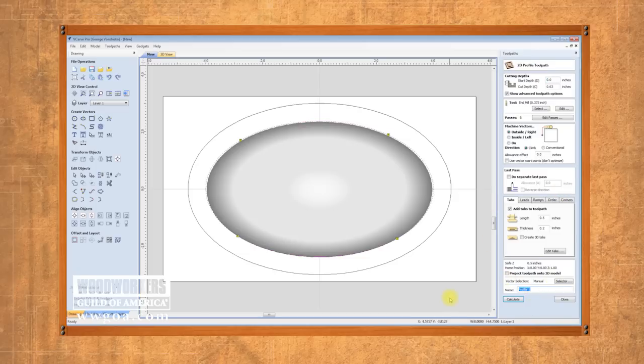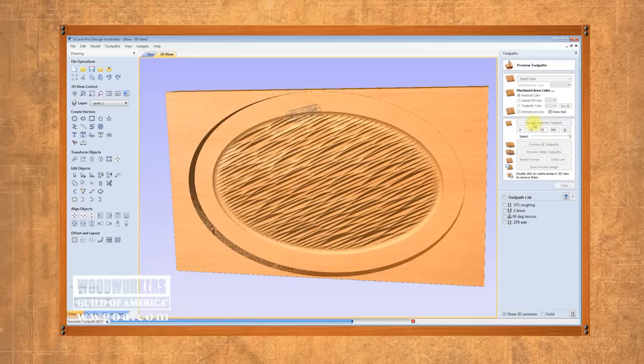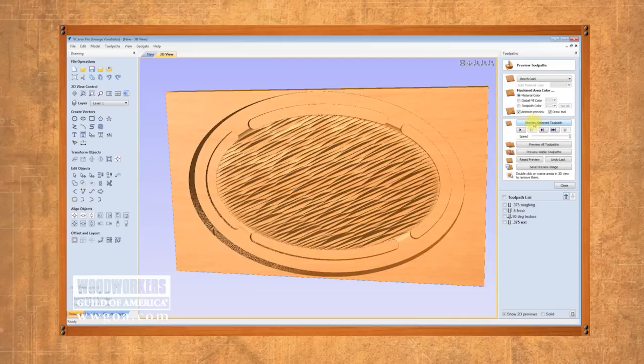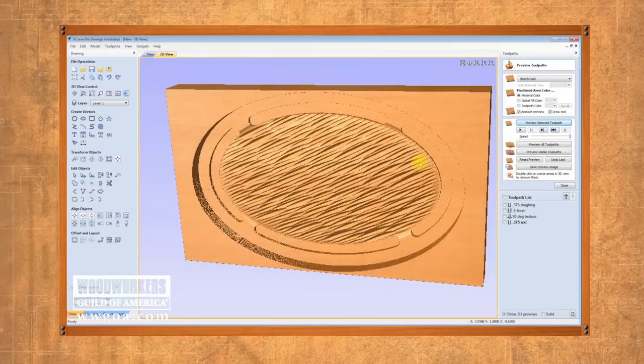Now this, it's again a .375 cutter, and this is our exterior. It's going to separate the lid from the body of the material. Now I can see from looking at this I made a mistake, so let's go back. What I'm looking at here is I don't think I set deeply enough on that cut. So let's go ahead and preview it, and I will tell if I'm right or not. Yep, it's not deep enough. It's too shallow. It's not cut through.